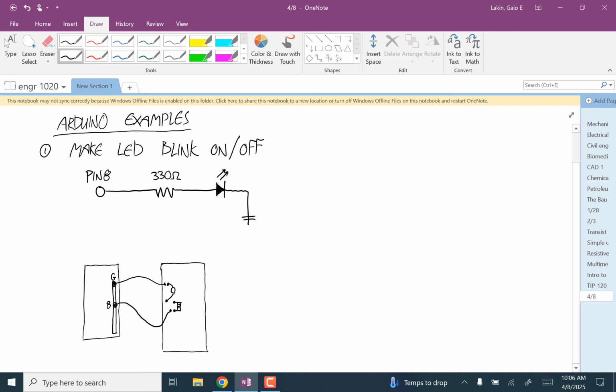Remember that LED stands for light emitting diode. And a diode allows current to flow one direction but not the other direction. And so you have to know which direction an LED allows current to flow. Let me get mine out. If you get one out, we're doing the small red LEDs, not those big, huge ones. You'll notice that one of the two wires is shorter and one is longer.